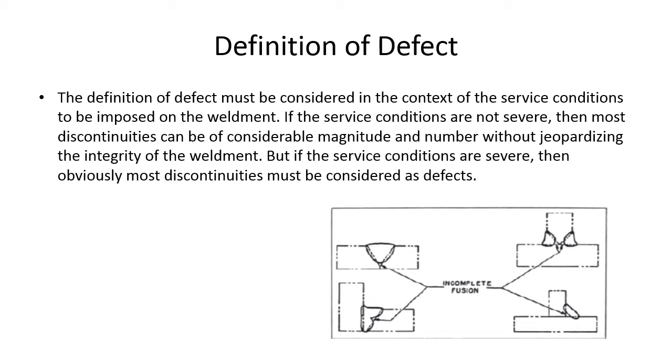The boiler and pressure vessel codes, ASME Section 1, which is boilers, B31.1, which is power piping, and B31.3, which is process piping. Those have different inspection criteria than, let's say, AWS D1.1 structural steel. And for structural steel, you have different criteria for static loading or cyclical loading. AWS D1.1 is different than D1.5, which is the bridge welding code, because there's a whole host of other different problems that come with bridges, the cyclical loading, wind loading. I don't even know half of the stuff that goes on in the bridge welding code.